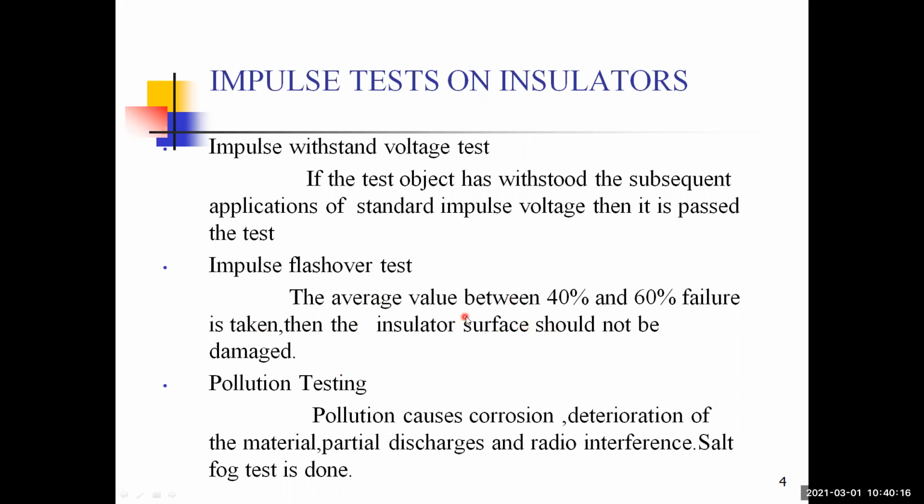By applying the average value between 40 to 50% of the voltage, then we have to check whether it is a failure or it's withstanding, the failure of the device or withstanding of the device. That is the impulse flashover test. And then pollution testing.